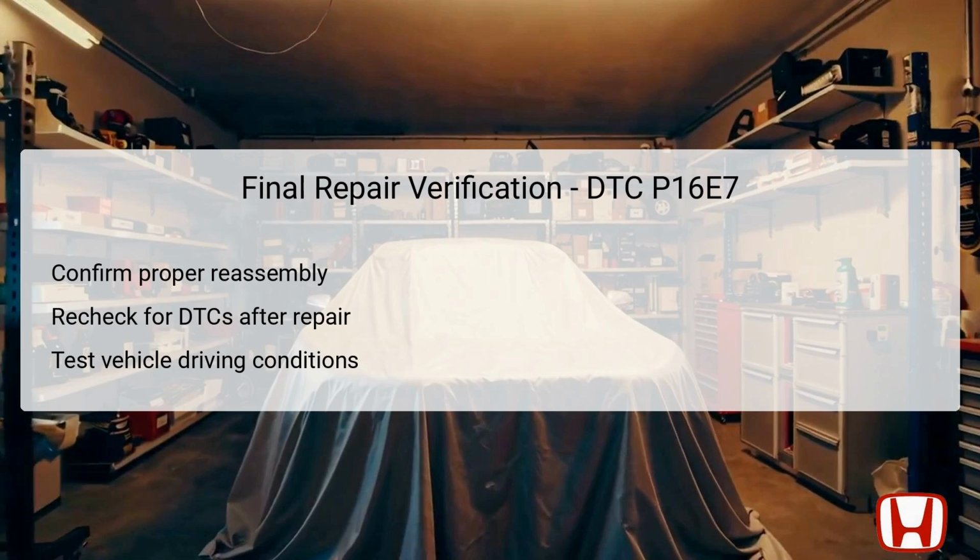The verification doesn't stop here. You also want to execute a road test under normal driving conditions to verify that the battery blower is functioning as intended and that no related fault codes have returned. This comprehensive approach makes certain that all issues have been addressed, providing peace of mind to both the technician and the vehicle owner that the problem has been thoroughly resolved.